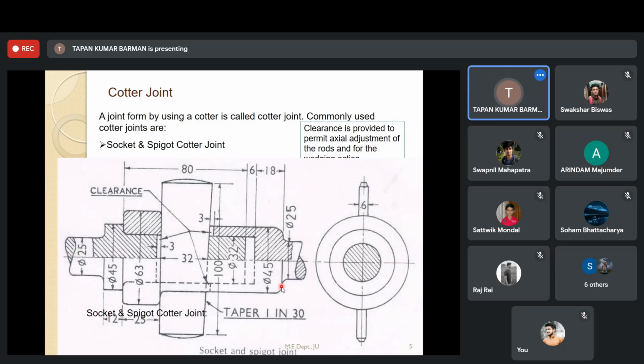When you look for the dimension of this object, you cannot find any dimension for this one because I do not know the exact dimension of this extension. So arbitrarily we have taken one length, and there we have shown a break line. So here also we have cut the object. When we have cut the object here, we need to provide hatch lines.